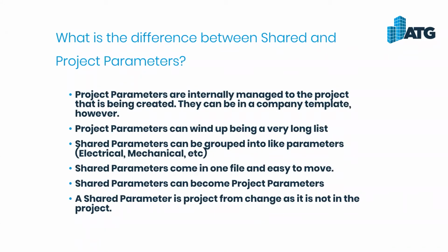Also, parameters can be combined into one. I've seen from typically third-party vendors, sometimes they have a shared parameter file that they give out to companies that are maybe utilizing their third-party software or some type of add-in, and you want to add that into your shared parameter file. So you want to combine those. You want to only really have one shared parameter file for a company.